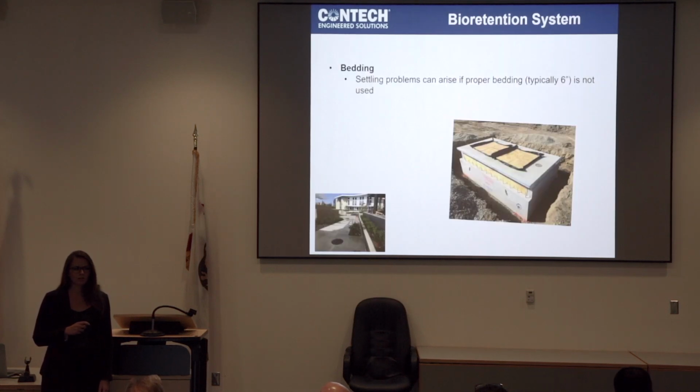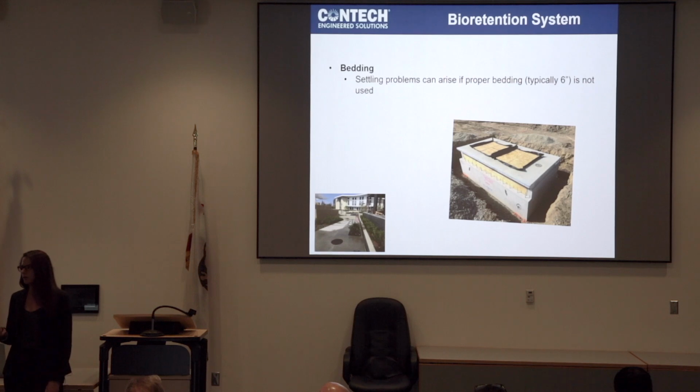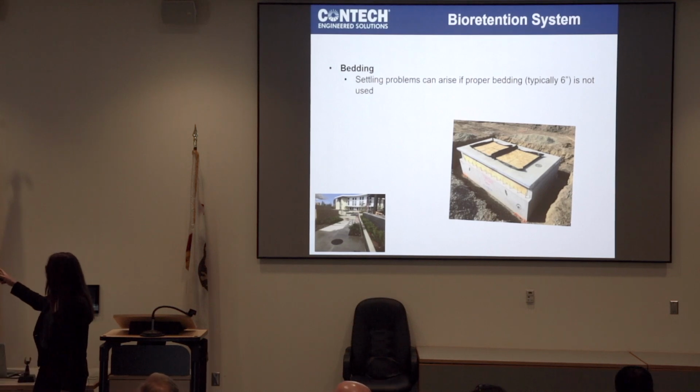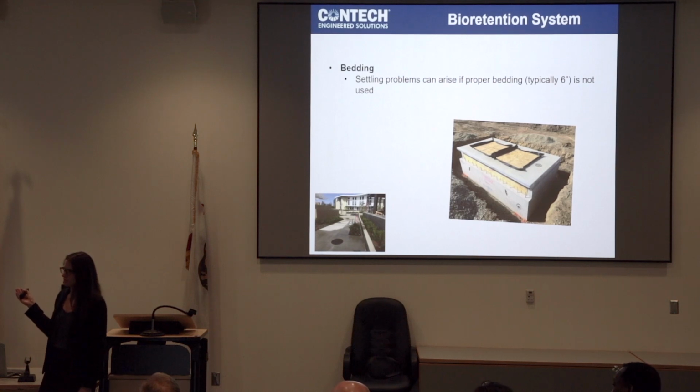Any questions on installation of precast structures so far? Yeah, David? Are any of yours included with media inside already when they're delivered to the site, which would increase the weight? Yeah, and that will be included on the drawing as well. For example, if you see a filtration system or biofiltration system, it will note if the media is included.